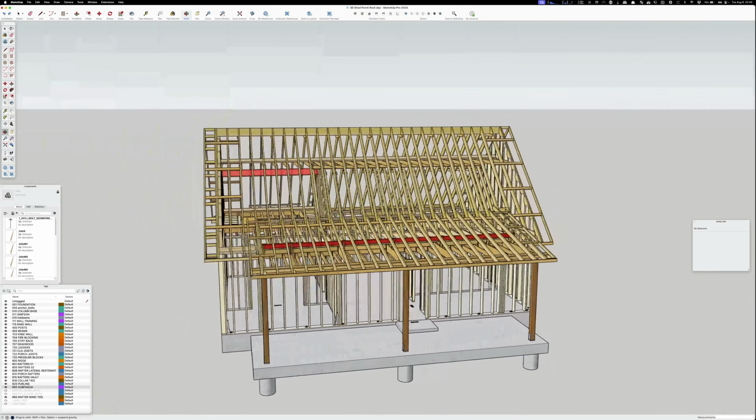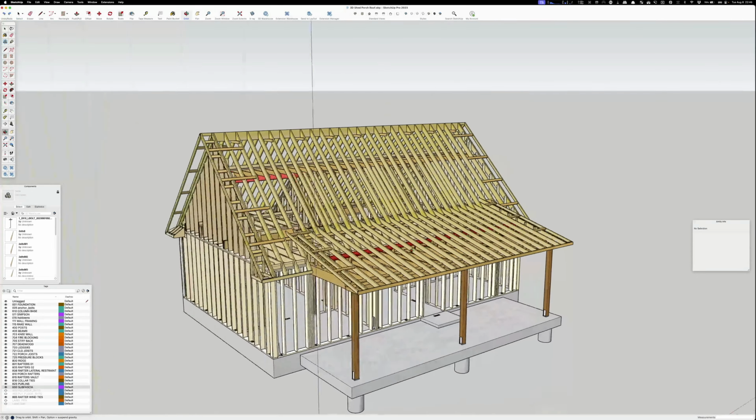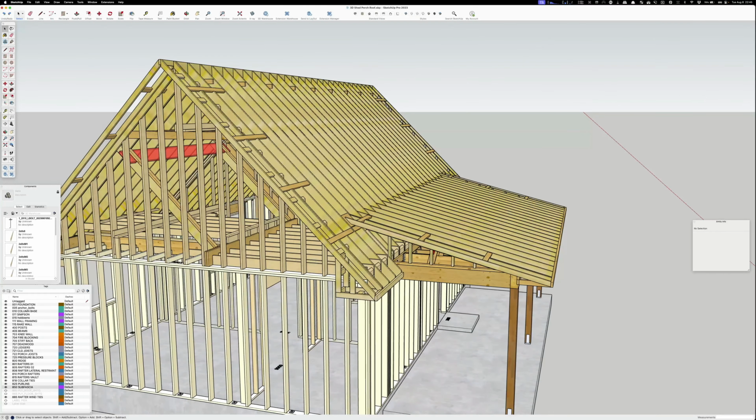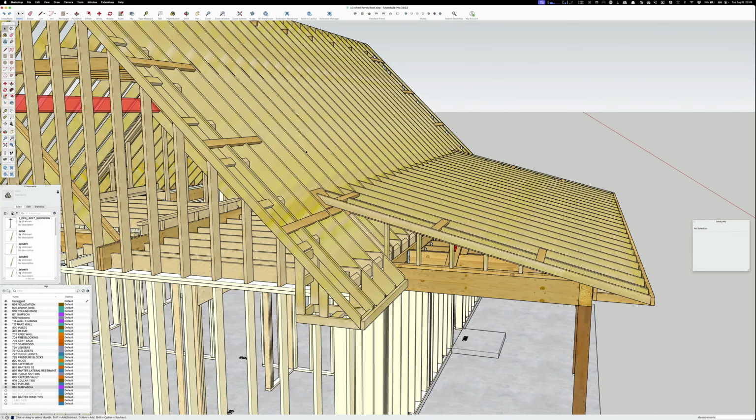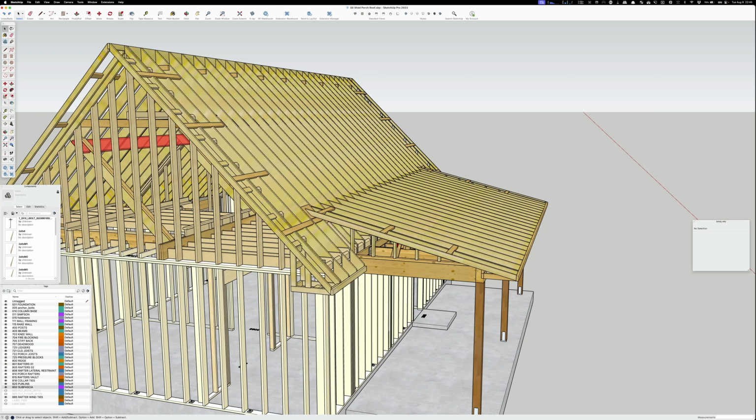The nice thing, okay, so that's another thing. Chief, the length of the rafters, they measure out to the outside of the roof plane, and that's not correct. A rafter is measured from the outside of framing to the face of the ridge. And then you add an extra bit for the tail.